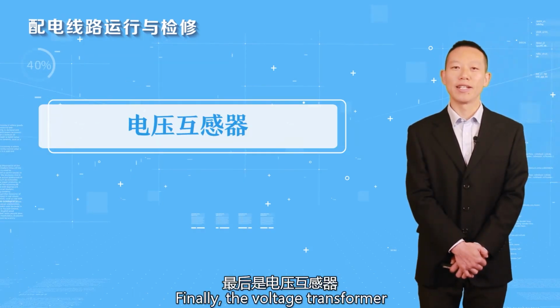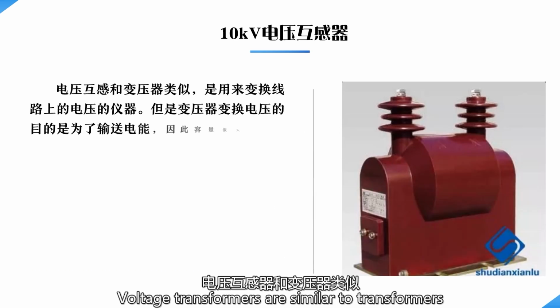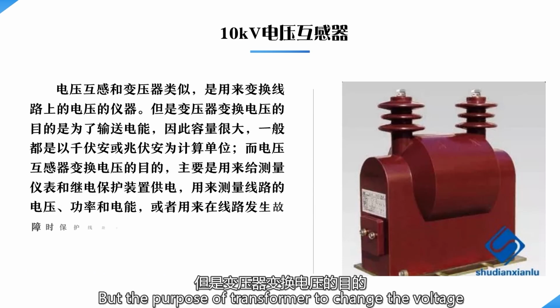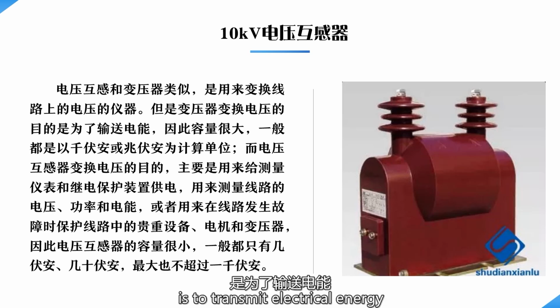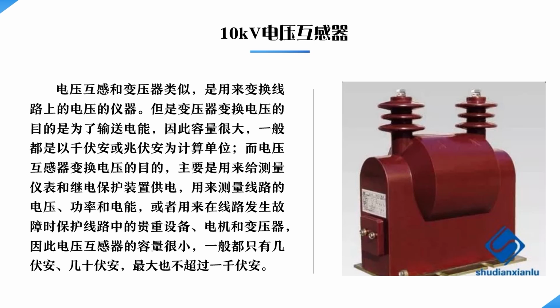Finally, the voltage transformers. Voltage transformers are similar to power transformers. It is used to change the voltage on the line, but the purpose of the power transformer changing the voltage is to transmit electrical energy. Therefore, their capacity is very large. They are usually measured in kilovolt-amperes or megavolt-amperes.